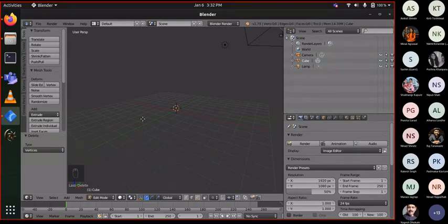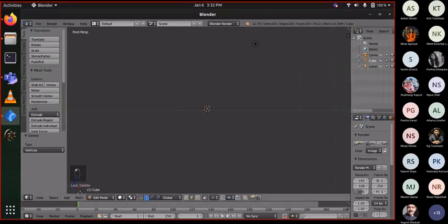So when you press 1, let me add a mesh so that you can get a clear understanding of this. Okay, so this is the official mascot of Blender. It has its own name, Susan. So now when you press 1, you can see we are in a front view. We are seeing its face. The numpad 3 key gives you the side view of that object.